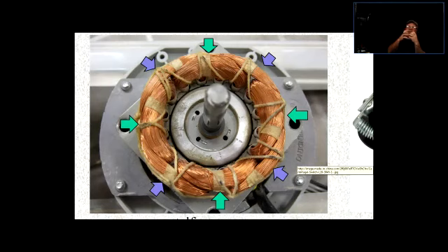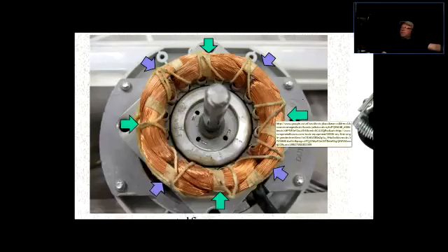So there are no mechanical things supplying the power to it. Everything is happening by the magnetic field. Okay? So all you have to deal with mechanically is the bearings and mountings and all that stuff. So I would say the maintenance-free life would be longer for the induction motor, for that reason.